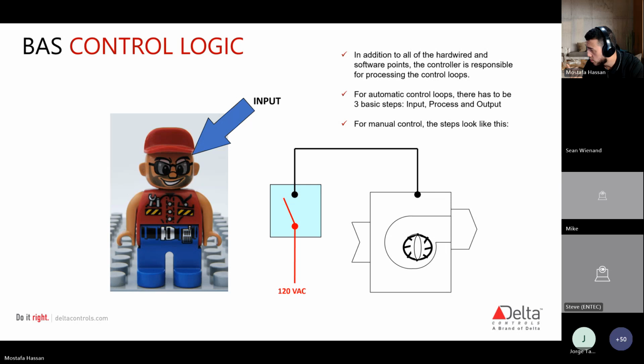Low temperature. Thomas, is that low temperature? Is that what you're saying in the chat? Yes. Okay. Low temperature. Yeah, it reacts to a small area of cold air, so that you prevent stratification from freezing a coil. Correct. As opposed to an averaging sensor, you could have a great average temperature but still have stratification. Correct. Does that go back to carry where it's like use one or the other or use both?